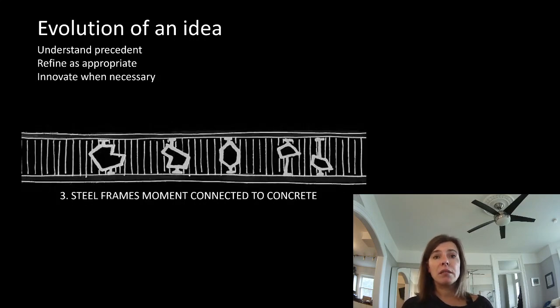So we said, all right, stick with your basic, simple method where you don't have windows. No problem. We'll build steel frames everywhere you have a window, and they are locally, structurally designed, and those can just get installed and the windows can be put in. The problem with this was that we needed moment connections top and bottom. Anything in the field that's a moment connection is a pain in the butt.